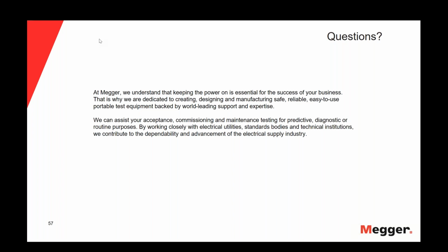All right, thank you, Robert. Additionally, what is the highest voltage for current VLF instruments? So that depends on the wave shape, as Javier described. The sinusoidal units go higher in terms of peak voltage, because that's the requirement mainly of IEEE 400.2. So if you look up in the table for the 69 kV cables, you'll find 119 kV peak.